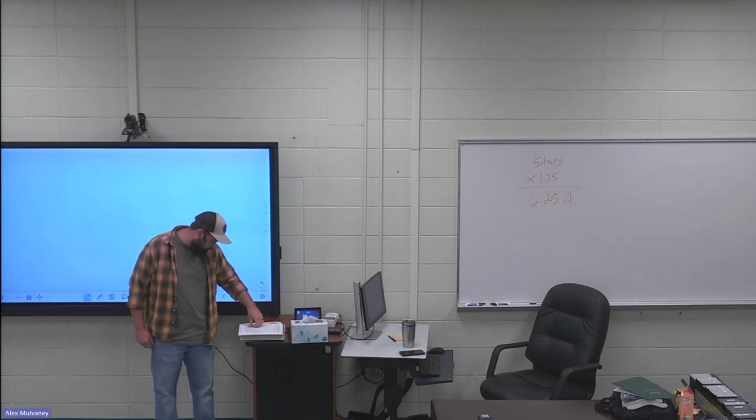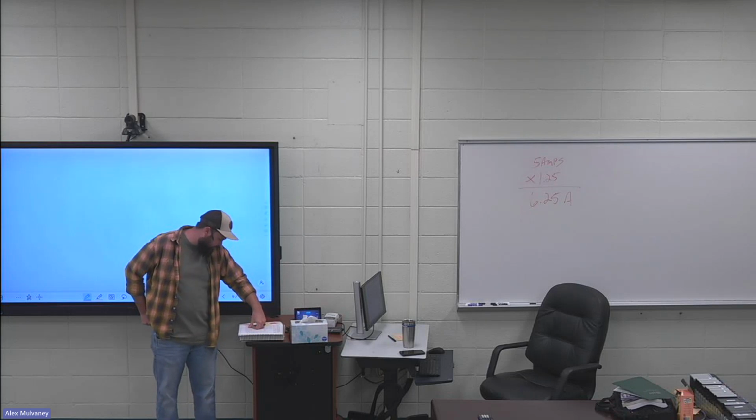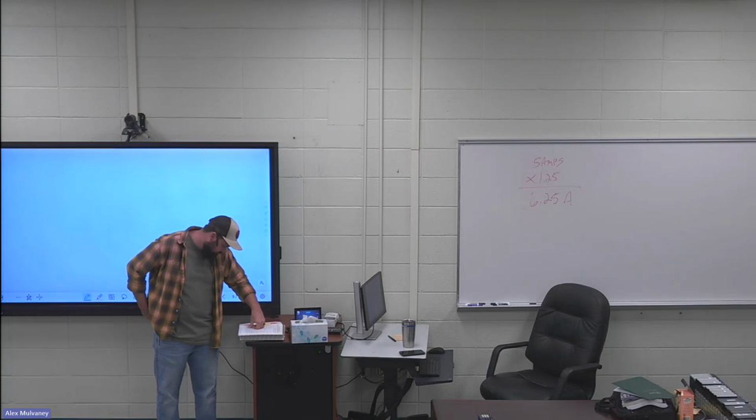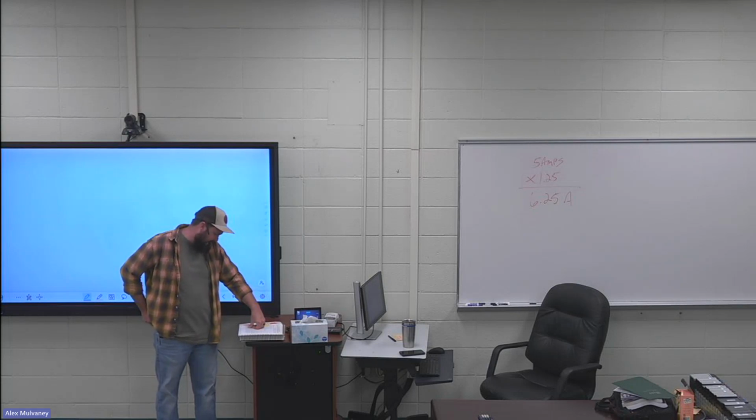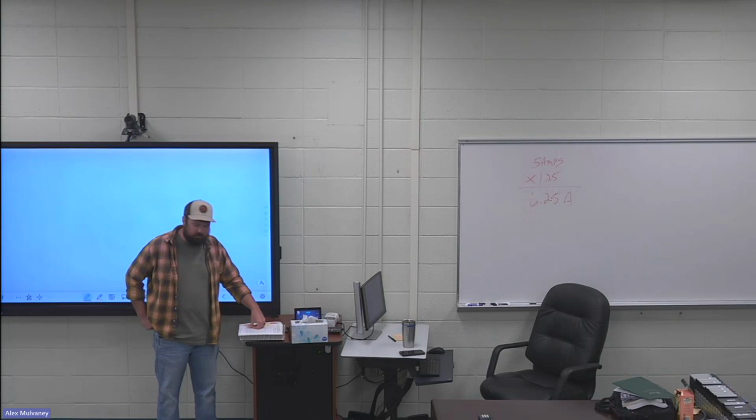The branch circuit load for one wall-mounted oven or counter-mounted cooking unit shall be the nameplate rating of the appliance. The branch circuit load for a counter-mounted cooking unit and not more than 2 wall-mounted units, all supplied from a single branch circuit and located in the same room, shall be calculated by adding the nameplate rating of the individual appliances and treating this total as equivalent to one range.